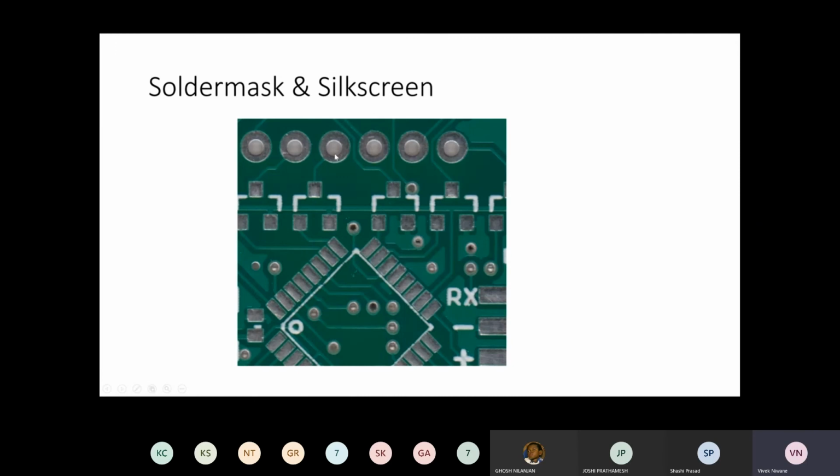And so in this particular case, I've got 2 types of pads. I have these sort of annular rings, which are around what I call a plated through hole. So a hole that's been drilled through the board and is plated with copper all the way through the board. Those are the sorts of things that we typically solder to. Now there's another type of through hole that we don't solder to. That's called a via. All right, this is a via right here. What that via is doing is it's connecting one layer to another. So it's connecting a wire on one layer to another layer.